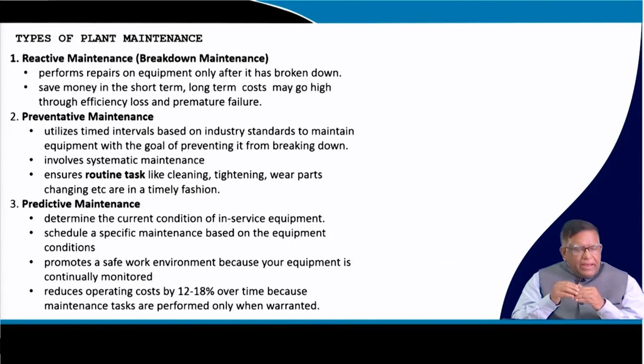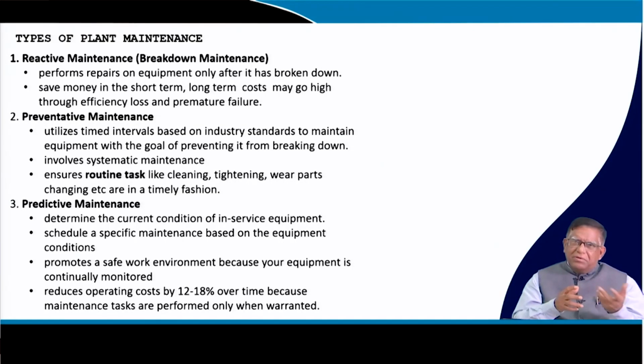That means in reactive or breakdown maintenance, you don't spend your time, you don't invest in buying some oil and putting it there. By that, your cost of operation, your cost of having that machine, is very low. If it does not break, fine, but if it breaks, then, in the bicycle case, your chain falls down and you cannot get to your class on time, or sometimes while putting the chain back up you will smear black spots all over your face. So that is exactly the cost.